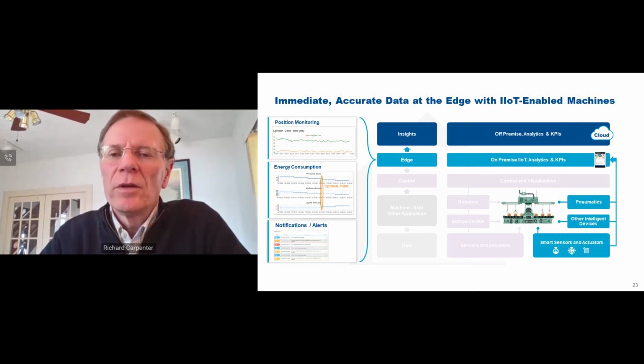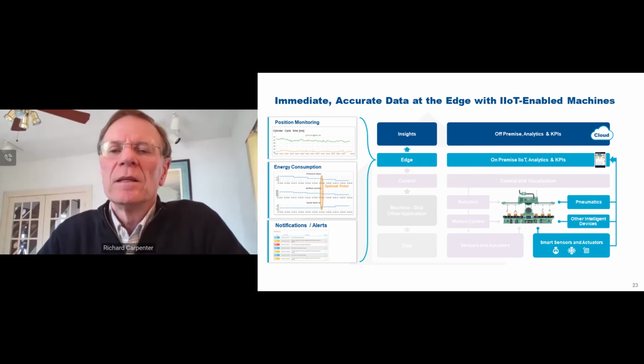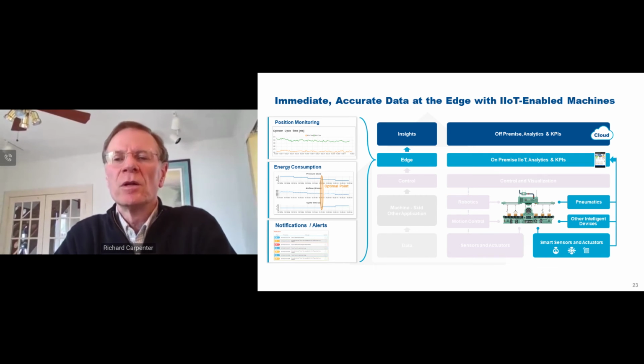There's no need to call the OEM that supplied the equipment. There's no need to risk voiding a warranty by opening up that PLC application. You can instrument the device, passively or directly to get this additional information from smart sensors. You can bring it into that edge analytic architecture and store it in these more little data oriented devices. You can run your analytics and get the insights to people via phone, via tablet, via web browser, or other mechanisms. And because it's an edge device, it can connect to both the control and the SCADA system simultaneously.